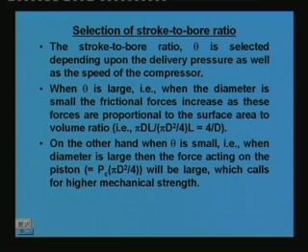That means you have to design a very strong piston, connecting rod and all that. That means the mechanical strength requirement increases as the diameter increases. In fact, it increases with the square of the diameter, and this factor becomes very important when Pc is high. So, these are the two limits. That means small theta means higher frictional losses and large theta means higher mechanical strength requirement.